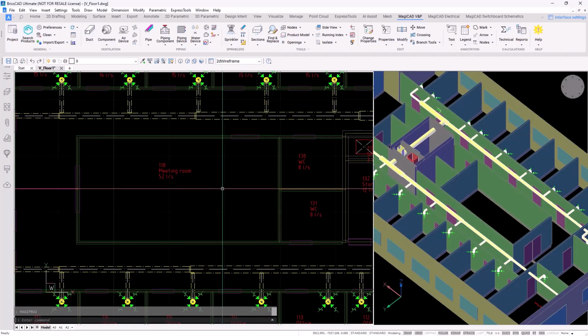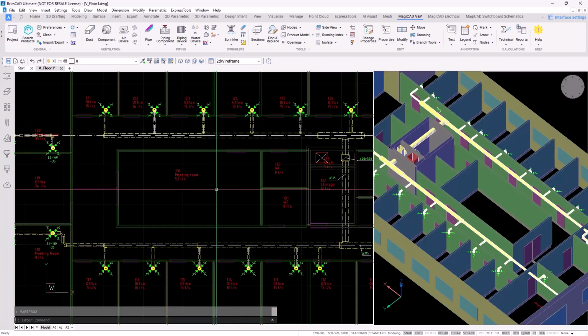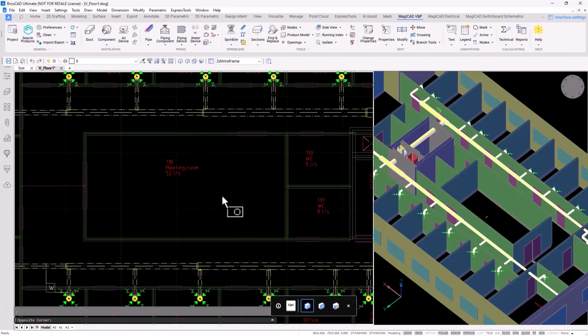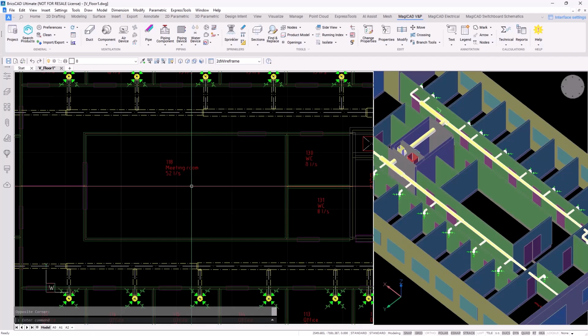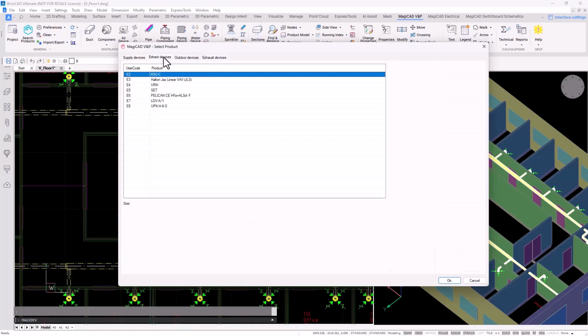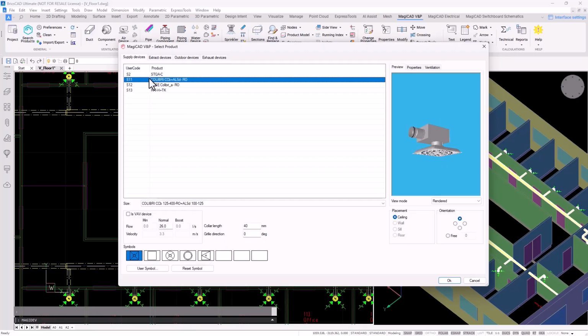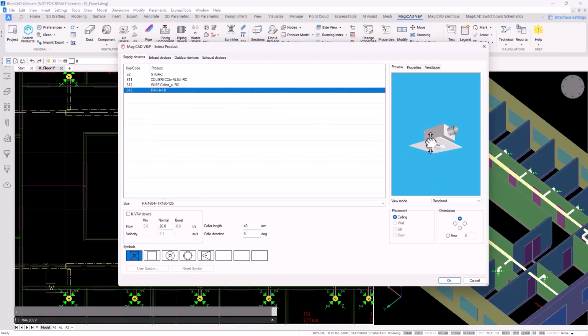We zoom in a bit. Here we have an office building with some offices and meeting rooms. Here we might have defined a supply air flow for this meeting room here. So let's begin the device installation by going to this air device tool here. And so let's just go on and select the device that we collected from the cloud. Here we have all the air device categories as tabs, and now we're in the supply device. So let's take the one that we selected.